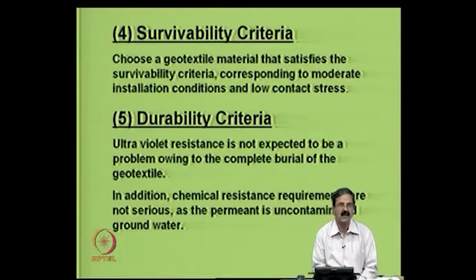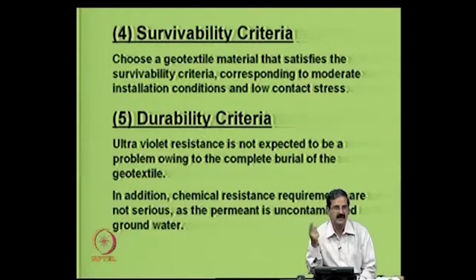Okay. Now, that condition is totally different, and you are trying to put a stone pitching also, and then the dropping of stones is there, which are somewhat different. So, the filter criteria, the chart you should use, will be different here if the flow is dynamic. Okay. So, these are all very important, and durability is also important if you consider particularly in this retaining wall problem,